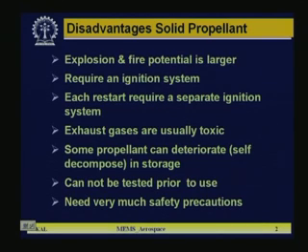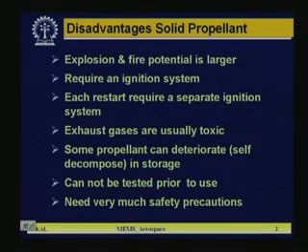Once you start it, then the second chamber you have to stop, and again if you have to fire the second chamber, you have to again put an ignition system. So each time you want to fire it, you need an ignition system. Exhaust gases are usually toxic in the case of solid propellant. Some propellant can deteriorate in storage, which is known as self decompose.